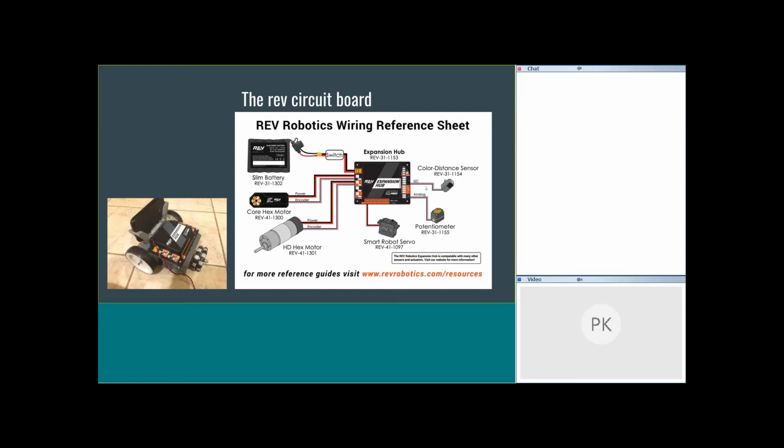For example, the digital sensors only give you yes or no, like Boolean in Java. So to this part, you connect all of the Boolean sensors. For example, a touch sensor, a sensor like a pressure plate, things that can only give you yes or no. Then there's analog sensors, which are things like temperature sensors, distance sensors on the Lego, things like that. So that's the difference between digital and analog.